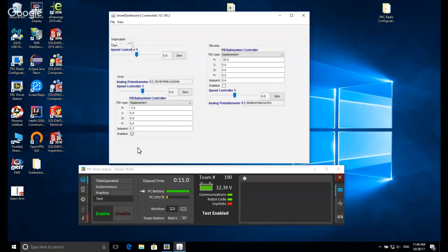So yeah, the key is it's going to predictable positions, and so you can set that up in advance because you know how high all the scoring things are in the field. So you can just write the program so it goes up to the right height, and then when you get there, it works, and you don't have to mess around with it. And so what you saw there was the PID loop is not tuned right now, so it's going to jitter a little bit.